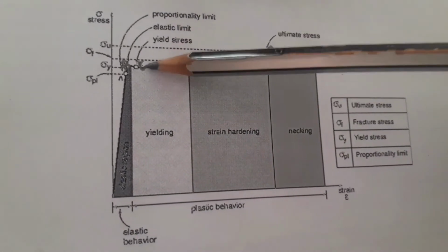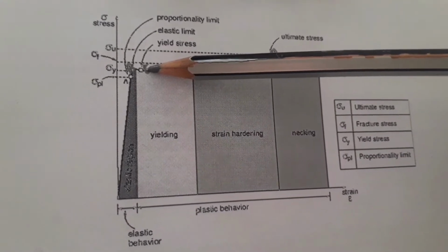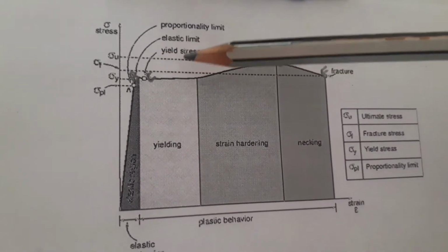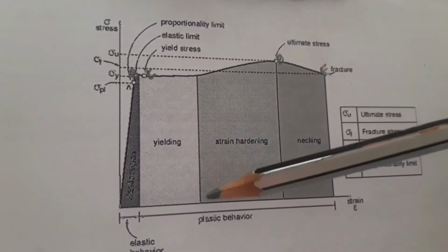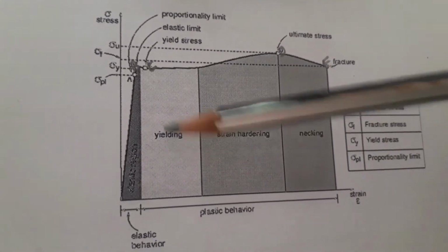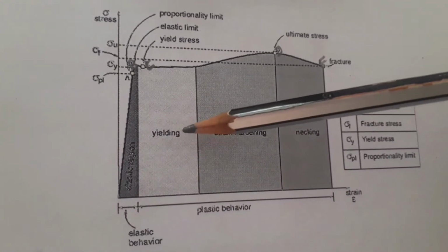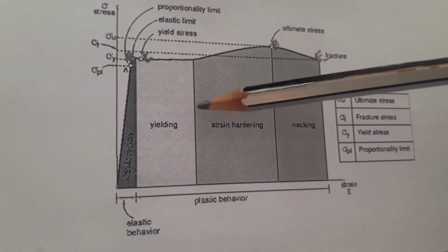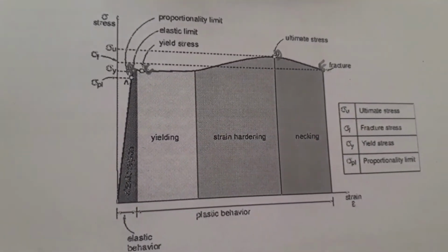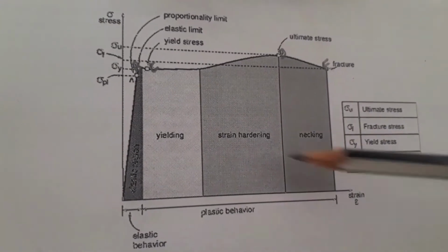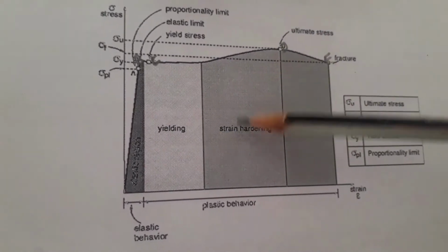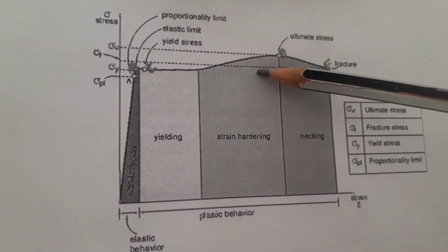Next one is the C. So this is called the material hardening area. If the stress is increased further, the increasing number of upright dislocations formed in the crystal lattice prevents the movement of previous sliding dislocations. At the same time, the stress in the crystal lattice continues to increase, which causes hardening of the material. Here the metal becomes stronger as the strain increases, hence it is called strain hardening. This area is strain hardening.